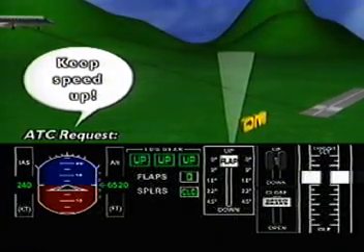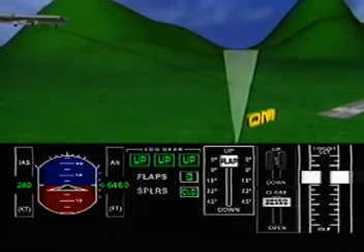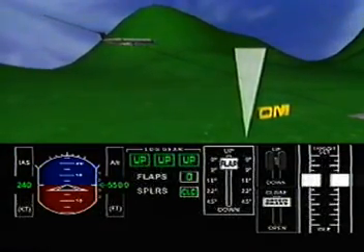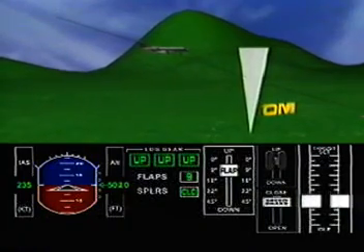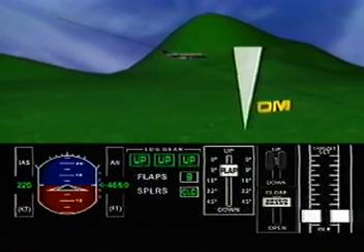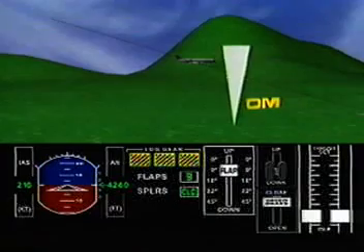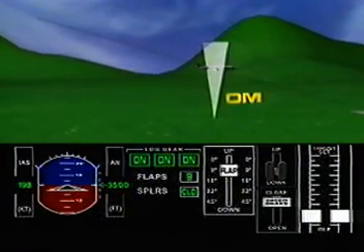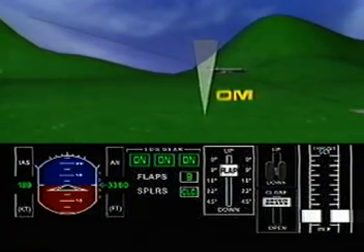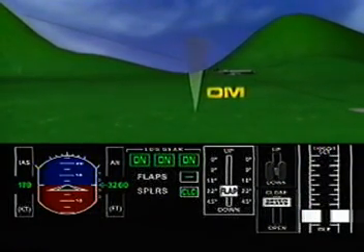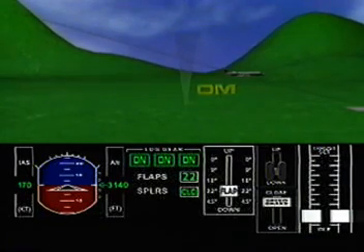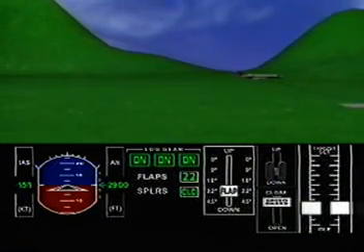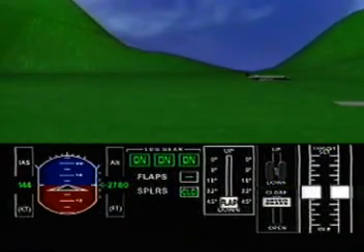Follow on the animated profile a typical, well-timed high-speed approach. Select flaps 9 degrees at approximately 3 miles prior to intercepting the outer marker. Set gear down. Reduce power to idle. At 200 knots, ask for flaps 22 degrees. At 145 knots, ask for flaps 45 degrees.